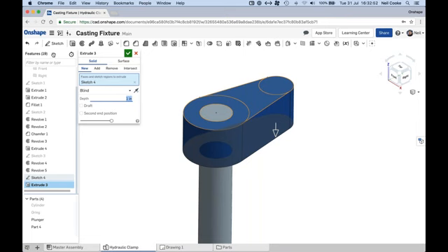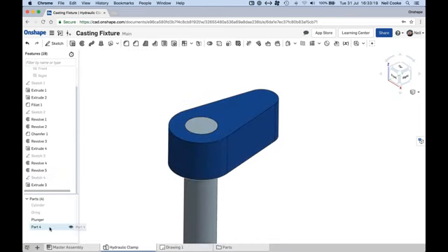So really only model parts together if they are related. If they're completely unrelated parts, or they might be part of the same assembly but they don't actually physically touch each other, then consider creating multiple part studios. It'll just make the whole thing a little bit more efficient and a little bit easier to navigate. Okay, so from this one extrude command here, we've then created a brand new part, and that's called part 4. Now, the fact that this sketch is here, we can reuse that sketch and build any number of parts out of it.